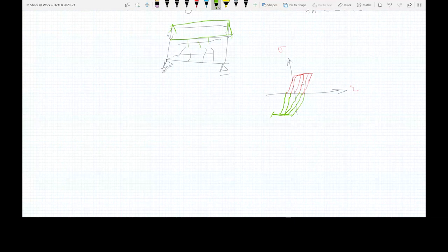And in this case, to understand the material behavior, you really need to know the history of this material behavior. Because if you look into this type of curve and you have a specific value for the stress, assuming that this is the stress you have, sigma 1, then for the same value of the stress, you have a range of values for the strain. So this is 1, 2, 3, 4, 5, and 6. So you have 6 values for the strain. So which one is the corresponding one? Of course, it's going to be dependent on the history of your loading.